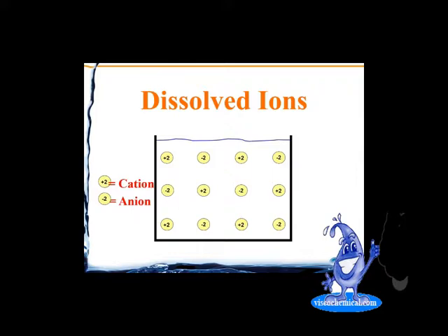So when we're talking about scaling, we're talking about ions, cations being positive ions and anions being negatively charged ions. The single charged ions are not going to give us a problem because they can get so close together that in an RO unit we're never going to scale with single charged ions. They will dissolve, sometimes even hundreds of thousands of milligrams per liter.